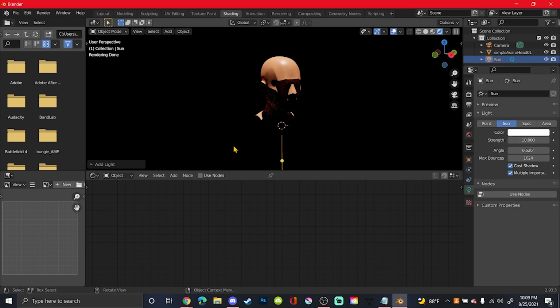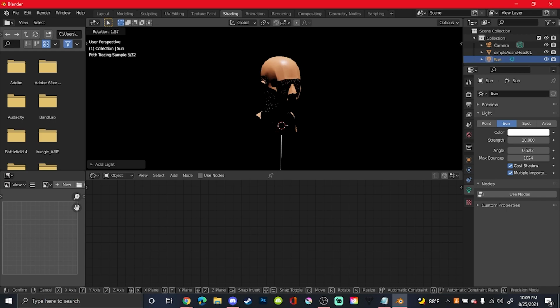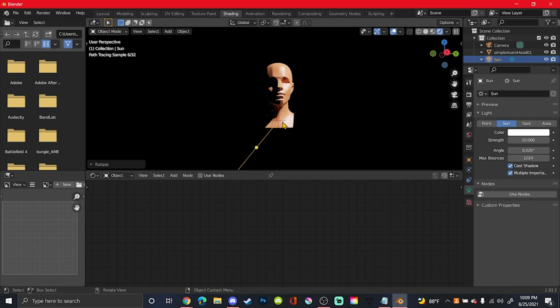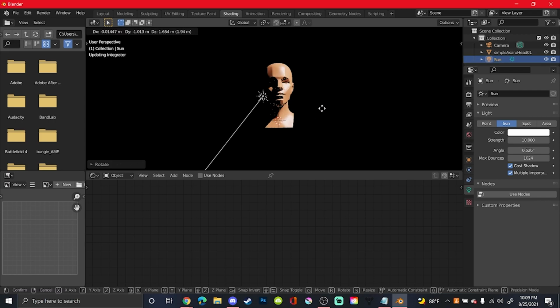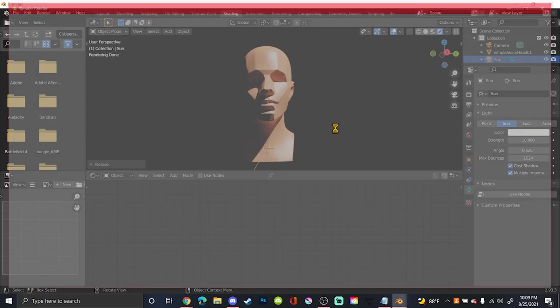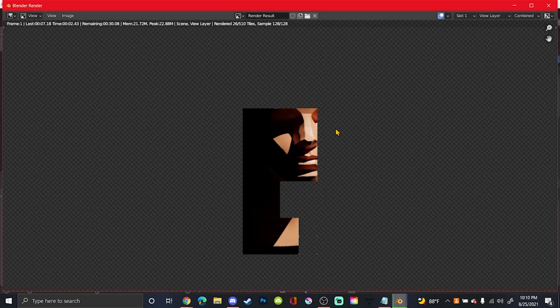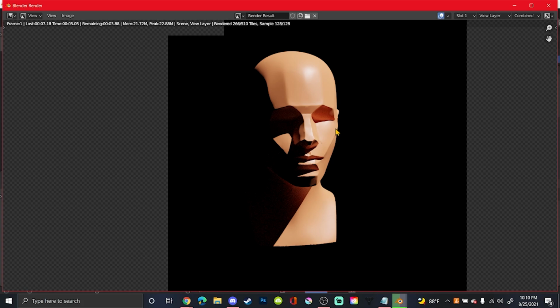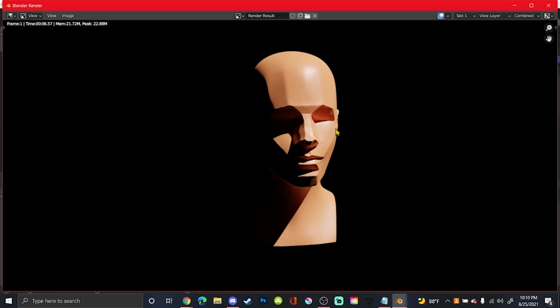So what I'm going to do is add a sun. And the sun is basically an environment light. So it spans over the whole environment from just sitting in one point. Moving it around doesn't change where it is, rotating it does. So now I have sunlight. If I turn it on, do the render, I get that. This method is really nice for advanced light reference. I really do recommend it to you. It's not limited to this model.